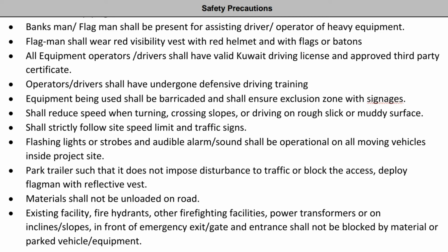Park the trailer such that it does not impose disturbance to traffic or block the access. Deploy a flagman with reflective vest. Materials shall not be unloaded on the road, existing facilities, fire hydrants, other firefighting facilities, power transformers, or on inclines, slopes, or in front of emergency exits. Gates and entrances shall not be blocked by material or parked vehicles.